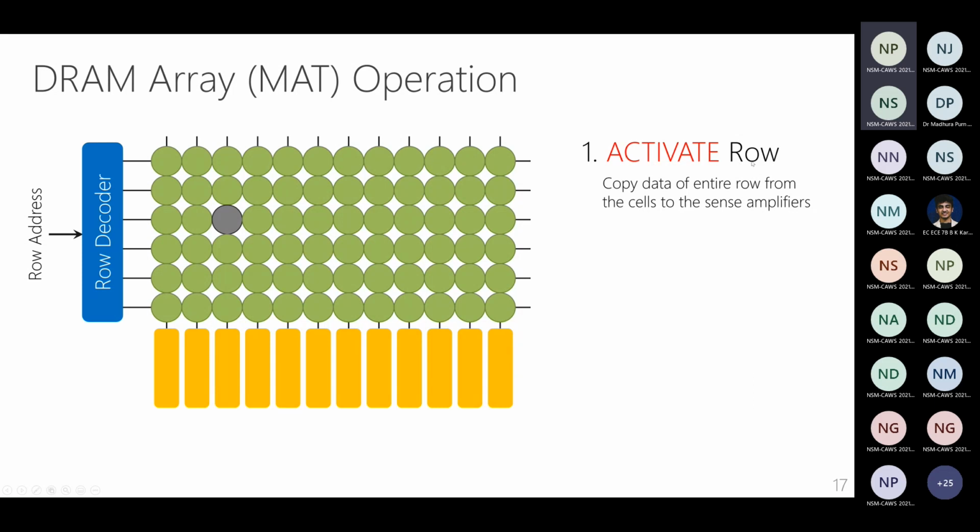This is again the memory controller operation that Professor Madhu discussed in the previous lecture. And what is this going to do? It is essentially going to transfer. As soon as I issue this activate to this particular row, the corresponding row address is going to be fed to the row decoder, and the row decoder is going to raise the word line of this entire row.